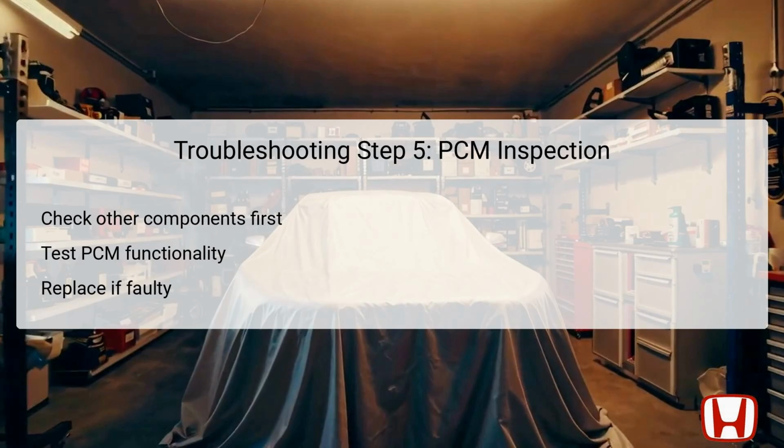The PCM plays a crucial role in managing the engine's performance by interpreting input signals and sending commands to various components, including the rocker arm oil control solenoid. A fault in the PCM can result in improper signals being sent, thus creating performance issues reflected by DTC P2654. Technicians must carry out thorough diagnostics to validate the PCM's functionality, and if deemed faulty, must replace it to restore the vehicle to optimal performance.